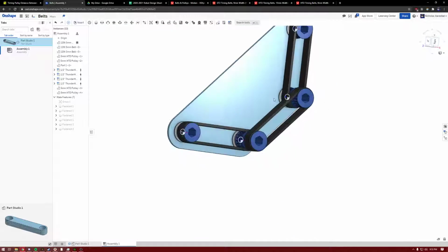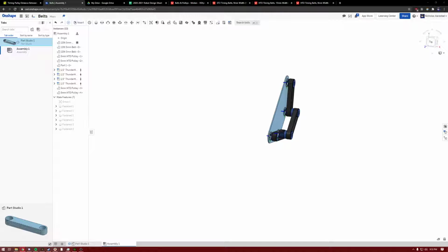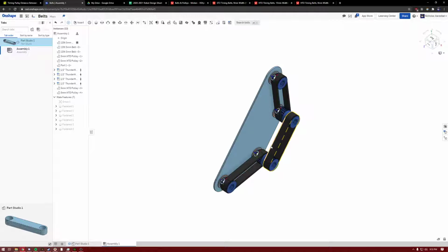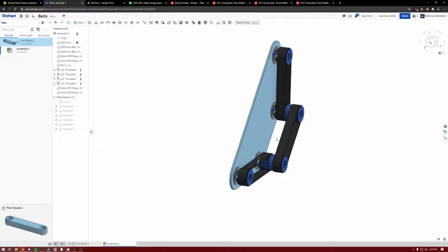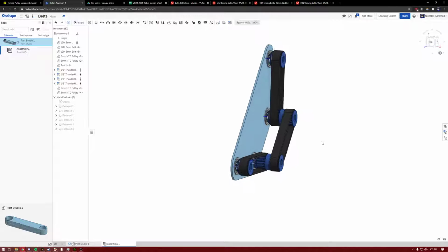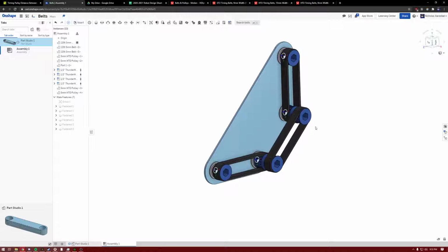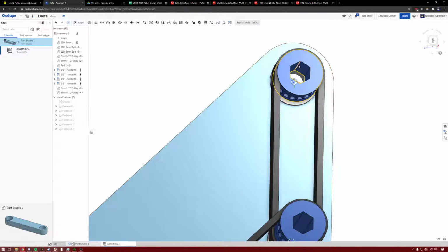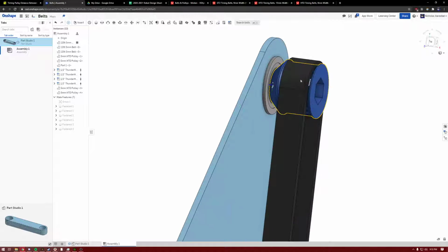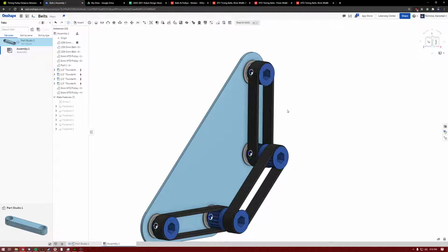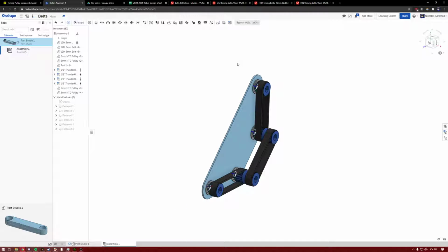I was going to give you a few different pieces of advice on 3D printing and stuff like that. So one, don't be afraid of 3D printing pulleys. Almost every pulley in FRC can be 3D printed. High load stuff, maybe not. But the vast majority of stuff that you want to print in FRC, you can print with a pulley. Sometimes you have to be careful to expand things or reinforce it. But generally you can print it in FRC. That's part of what makes these things simpler.